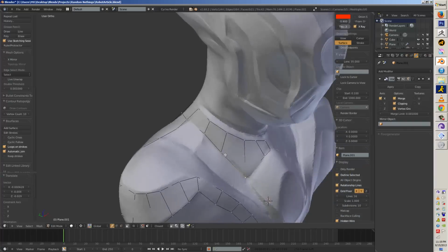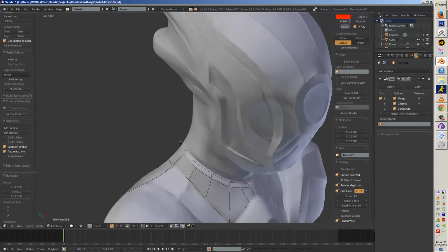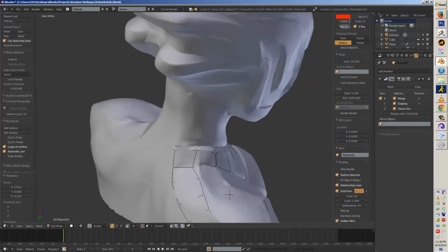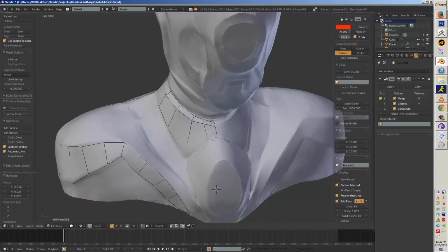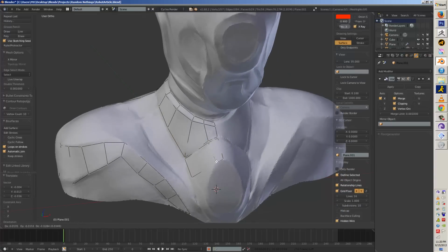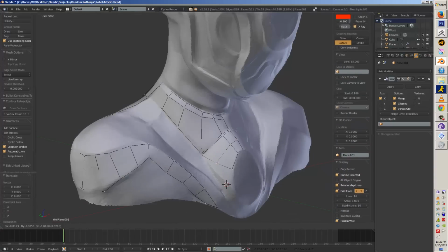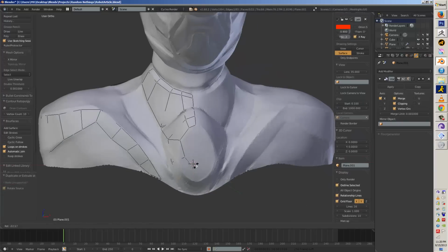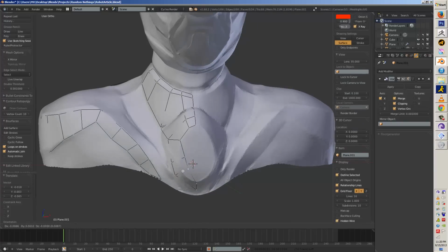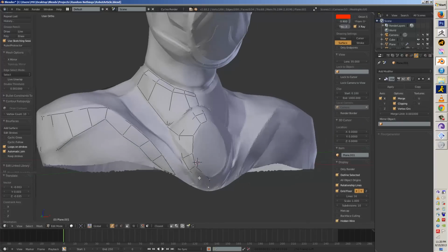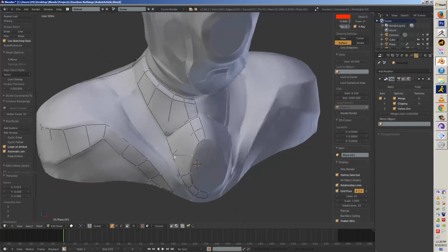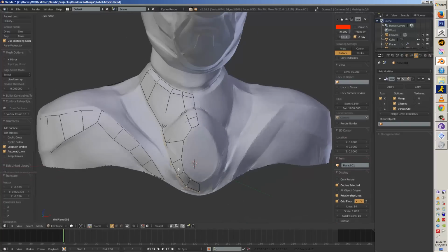So whenever I'm adding the geometry to retopologize something, all I'll do is just import a plane, just Shift A, add a plane, then in edit mode, just select all the edges and choose Alt M to merge at center, or delete them, or however you want to do it. But usually you want to start off with only enough geometry to just get you in there, but you don't want to make it too hard on yourself.